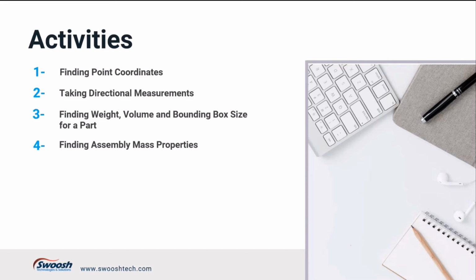A lot of our customers that have multiple 3D printers have different capabilities, different envelope sizes that the printers can handle, and they'll be looking for the bounding box size. So I want to show you how to get that. Some of you might be familiar with the bounding body feature. There's a bounding body as well as a bounding box, 2 different things. I'm planning to show you the bounding box that's part of the measure tool.